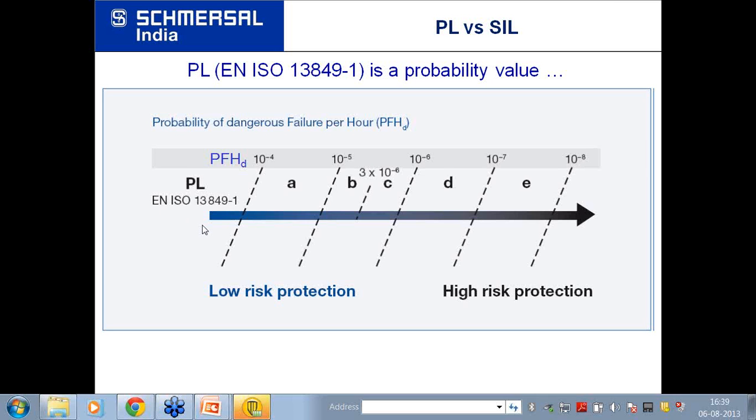Mr. Paresh Dalal has asked a very relevant question. From the safety point of view, which equipment should be used for interlocking of doors or flaps, limit switches or magnetic sensors? Sir, both can be used, provided the magnetic sensor is a magnetic safety sensor. It should not be a normal magnetic reed type switch. It should be a magnetic safety sensor, and the limit switches also should be of safety type with positive break contacts, the arrow in a circle mark.